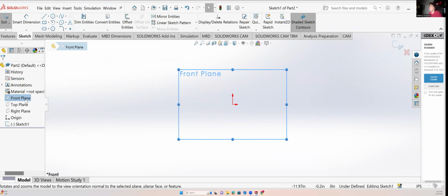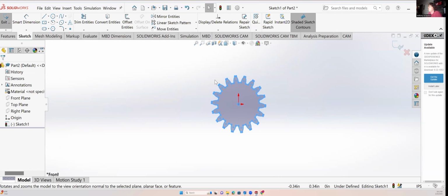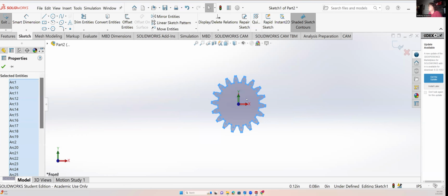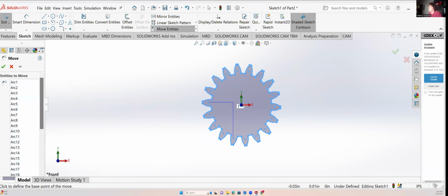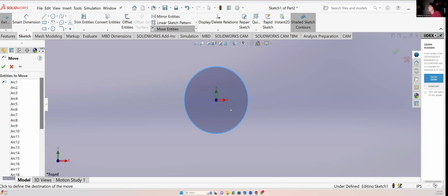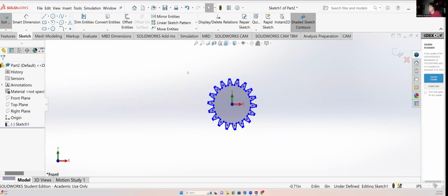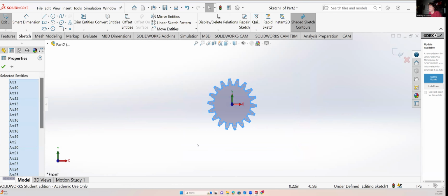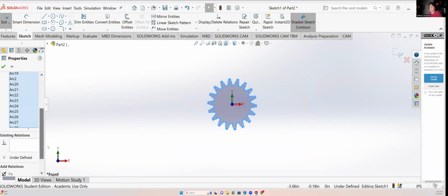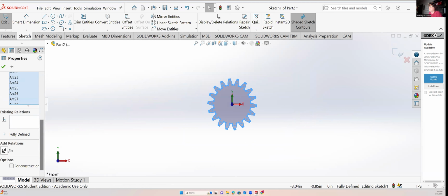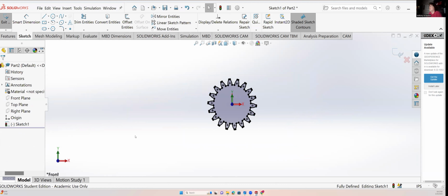Again, as we're in this sketch, we're gonna hit Control V. And then now what we're gonna do is move it around and just make sure that it is at the origin. And we're gonna go to the midpoint there, or the middle point, I should say. And then we're gonna come back to the origin just to make sure we're coincident. Probably didn't need to do that, but anyways, go in there, highlighting everything, and we're gonna make all those fixed. Okay, just like we've been doing.